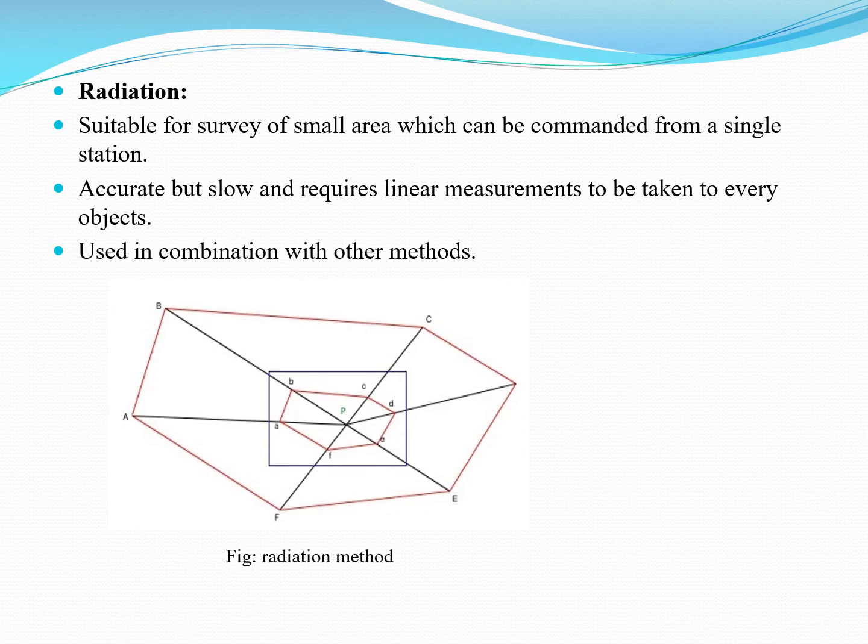By using the trough compass, first mark the north line at the right top of the sheet. After that the alidade touching the point P, ranging rods on points A, B, C, D, E and F are bisected and rays are drawn along the alidade.